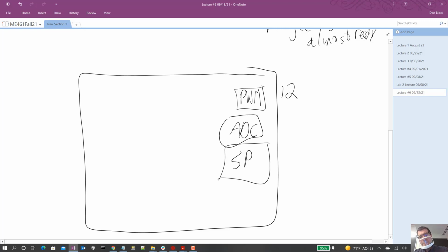Serial ports, we got SPI, we've got I2C, we've got UART. If we get even deeper, now we won't get into this, but there's peripherals for talking to an SD card. Okay, so you can plug in a little flash SD card into this guy if you set it up right. Our board does not have that. The red board does not bring out the pins to an SD card.